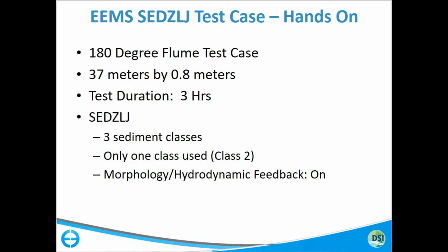and it's just a 3-hour simulation period. It literally runs on my machine in about 3 or 4 minutes for a run. We have it set up with 3 size classes. However, I'm only using class 2 right now. So classes 1 and 3 actually have no sediment configured. The water coming in has 0 concentration of TSS, so the only sediment in the system is the sediment in the bed initially.